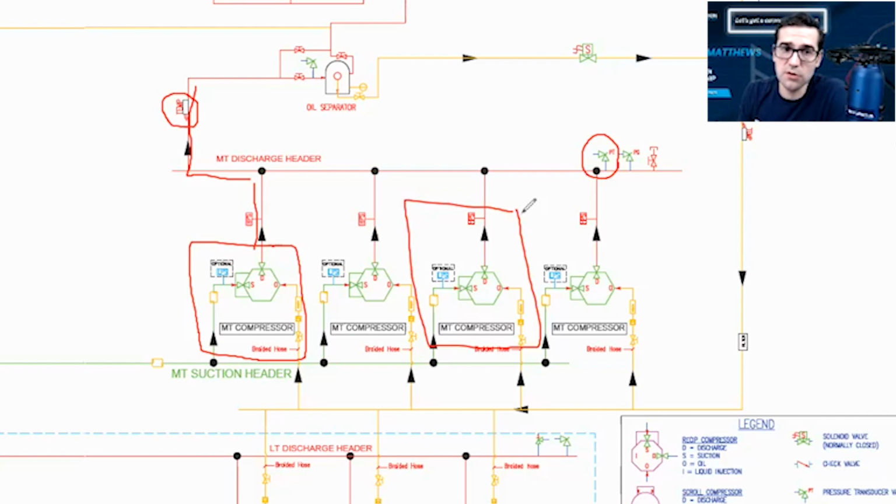And we know on CO₂ transcritical, you cannot use the normal gauges that are used today. You need a set of high pressure gauges. So important. I really believe that every site should just have its own, as long as the technicians don't take the stuff. It's for that rack. For the amount that rack costs, you should have one set of transcritical gauges there. And everybody should be taught how to use it, how to at least add gas to a system.